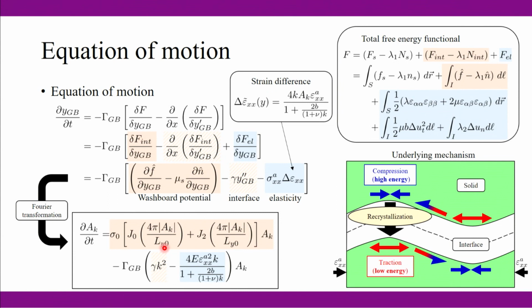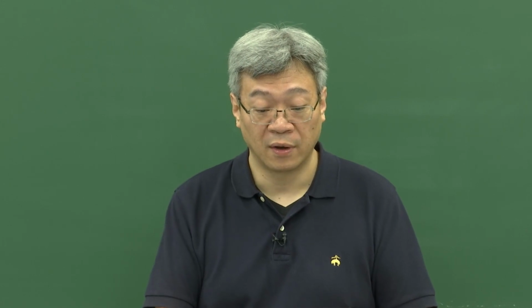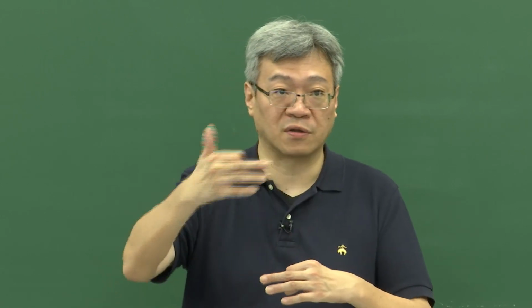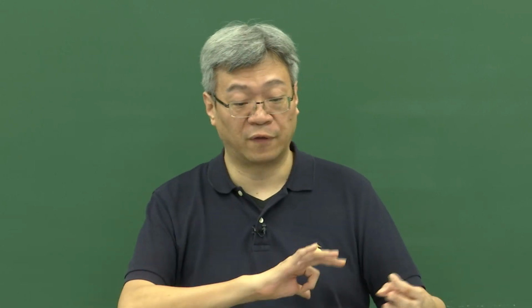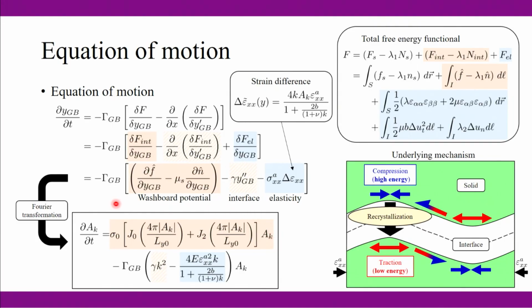But in addition to that, we have something else that's not in the general ATG derivation. You have on the top line here a term that does not depend on the wave number. You only have a term that depends on amplitude. And of course, that's from the washboard potential, right? Because when the amplitude is large, going across different spatial configurations of the coincidence site lattice, it's going to give you different push or different pull. So through derivation, we are showing this kind of Bessel function behavior, right? So it's quite different than the solid liquid case, and we are showing two different contributions.